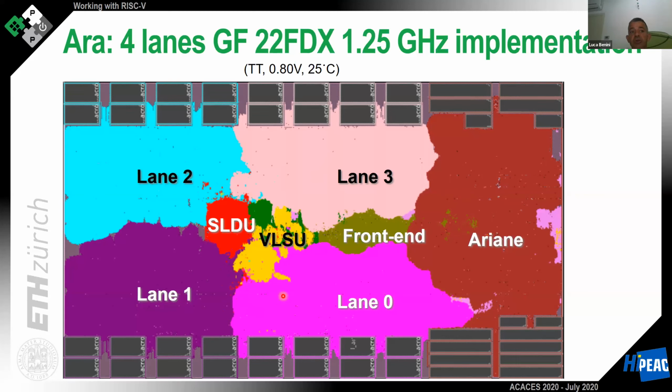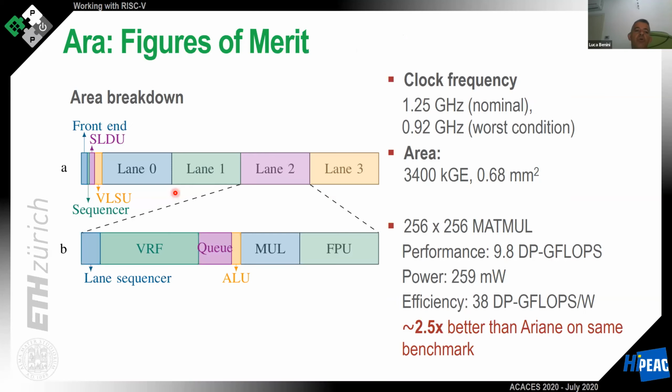So it means that if we can keep these execution units busy with high utilization, we'll get good performance and efficiency out of our silicon, because our silicon will do most of the time floating point operations, which is what we care about, and use 80% of the area to do floating point operations. Again, it means that we are using our silicon efficiently. So, in terms of implementation, the clock speed of Ariane and ARA can be matched. Actually, ARA is slightly faster than Ariane, but just a minor difference.